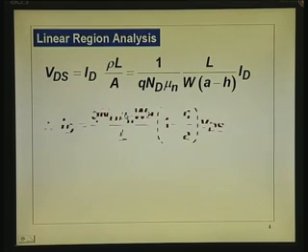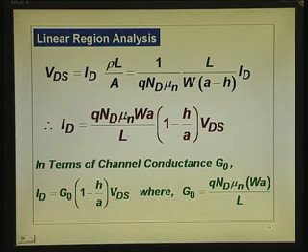Okay, that is channel resistance, and I put it as channel conductance, 1 by that. So, sigma into area by L, that is G naught. G naught is that quantity. I am writing that because it works out easy to write that one alone, instead of writing all these right through.